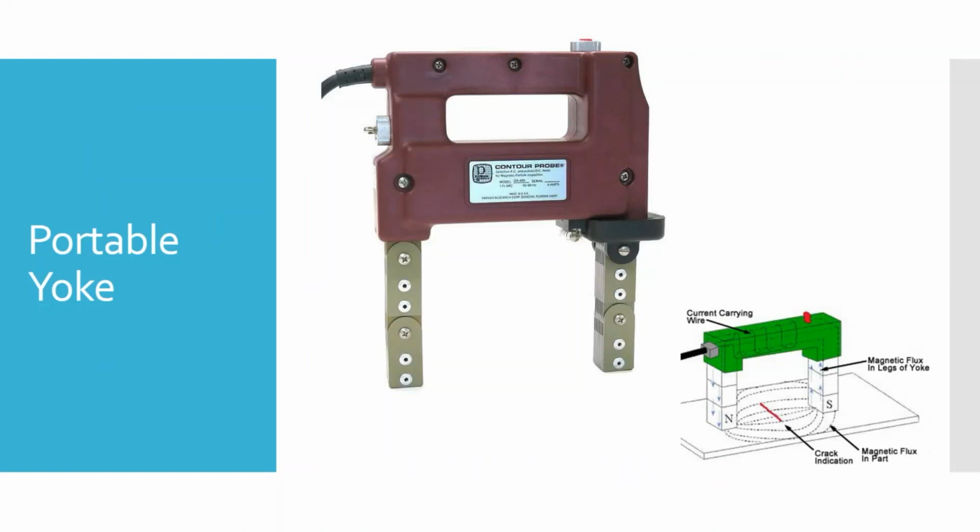That's how you're going to demagnetize parts on our bench: you're going to hold the part in the middle of the coil, turn the coil on, and draw the part out from the coil. And you'll be able to demagnetize it. So one way is to take the part and draw it away from the magnetic field. The other way is to take the magnetic field, if you have a yoke, and draw it away from the part. Or if it was the window frame, we'd have a flat surface.